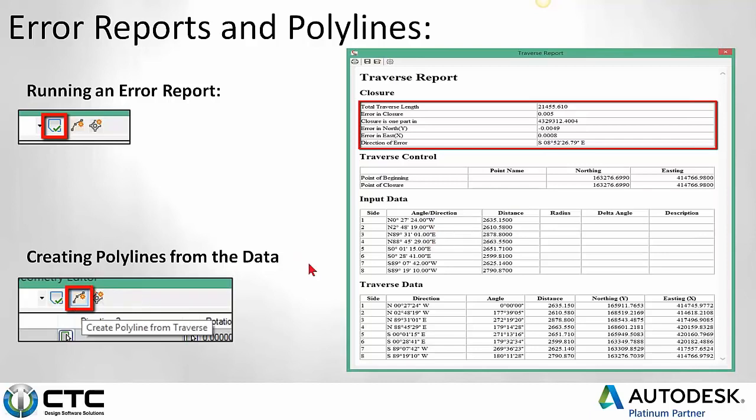But that would put a polyline in for all 8 legs, and then if I want, I can hit the next icon in there, and that will actually drop in a COGO point at the end of each leg, giving me the ability to export it out as a text file, CSV file, and then give it to my surveyors, and then they can point stake.